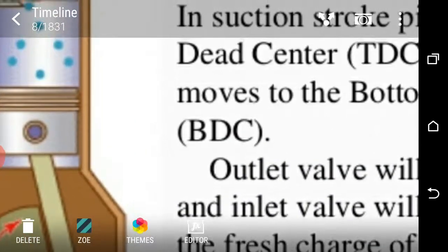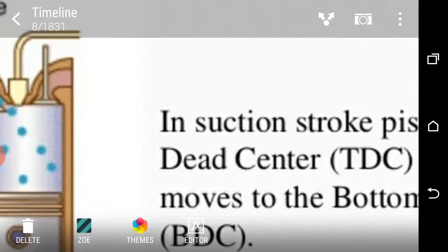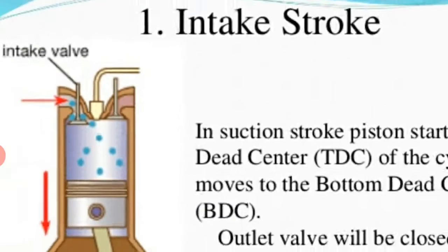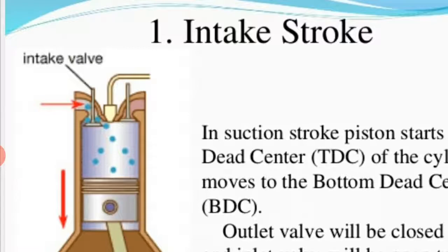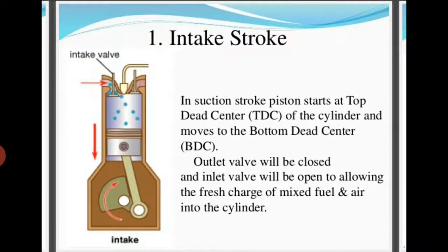Now in this suction stroke, the inlet valve opens, and during this stroke only air enters the engine cylinder. The exhaust valve remains closed. When the piston reaches the BDC, the suction stroke is completed as shown in the slide.